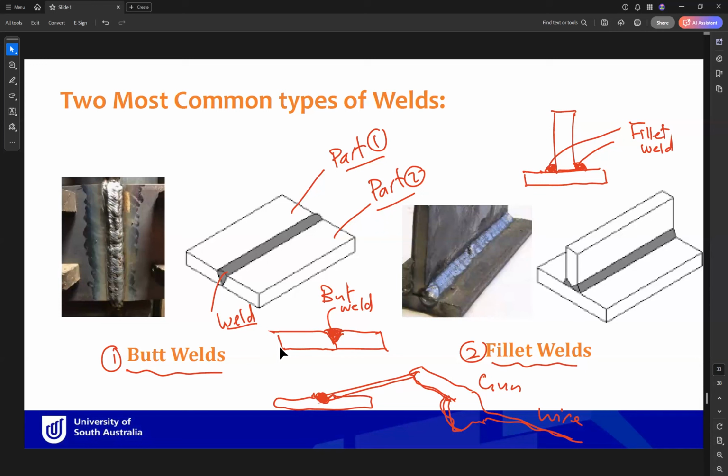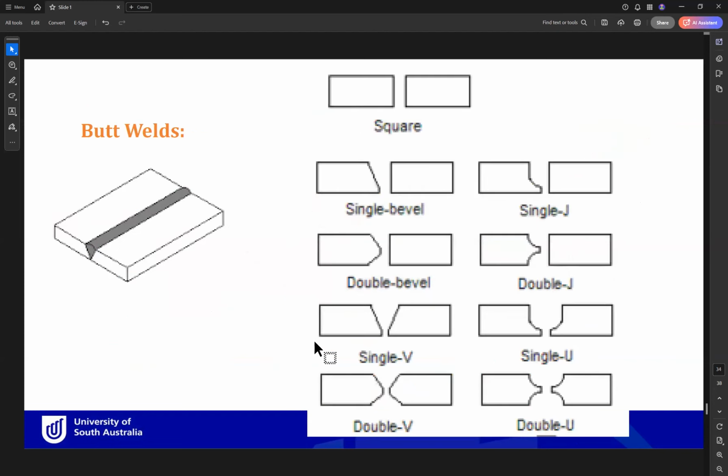Okay, so this is one type of connecting steel parts together. Instead of bolts, you can use welds, and you can search. One of the questions is what is the advantage of welding and what is the advantage of bolting connection. One clear advantage of the welded connection is you don't need to make holes to connect the members, because in bolted connection you need to make holes so that the bolts will go through the members or the elements. So you can search about the advantages and disadvantages of each type of connection.